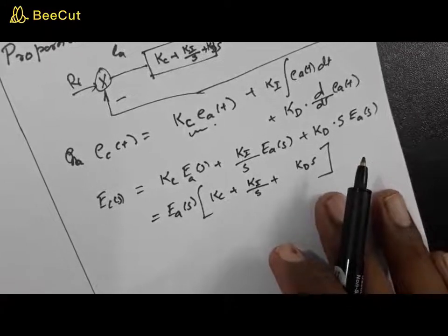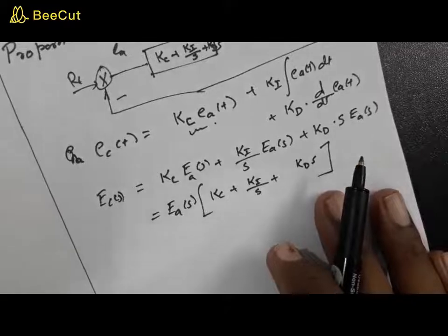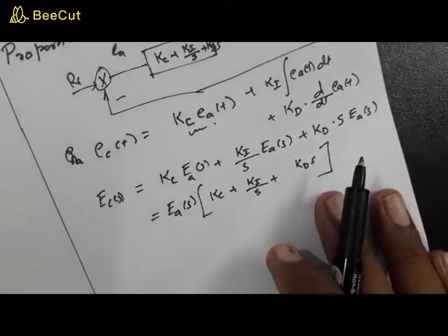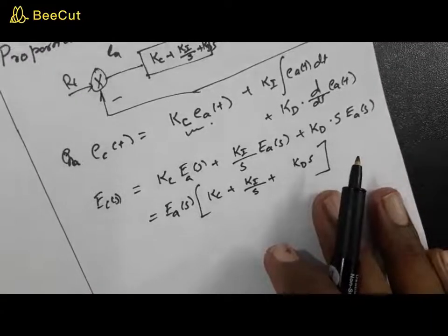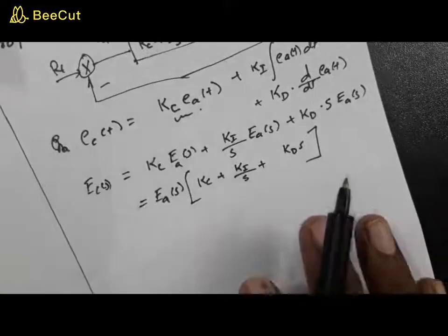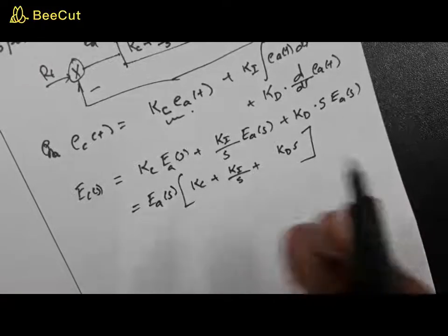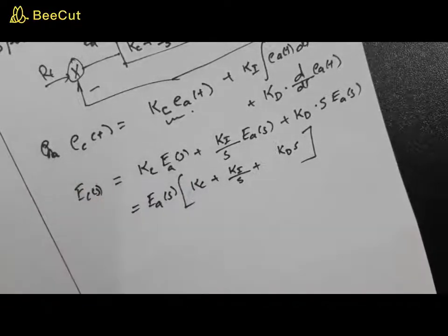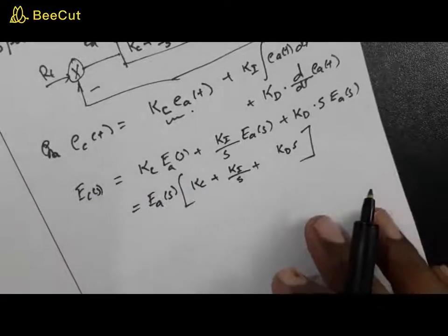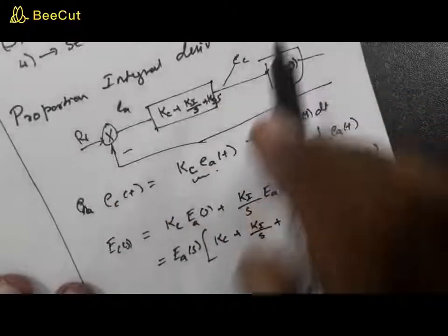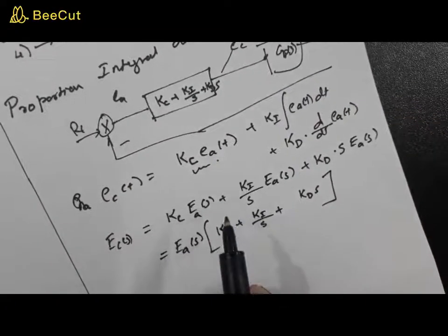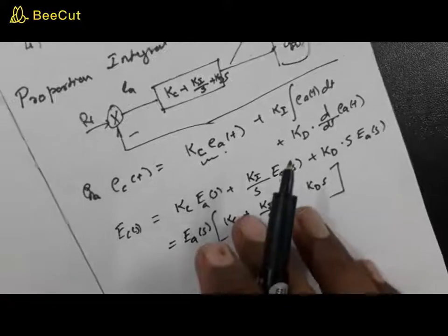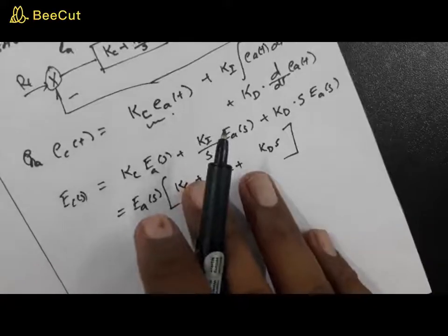So if you can put a limit to that increasing value of Ki, you can restrict the system from going to an unstable state. Giving all such restrictions, you can derive the advantages of each controller in a PID controller, so that this becomes a more effective controller as far as the performance is concerned.